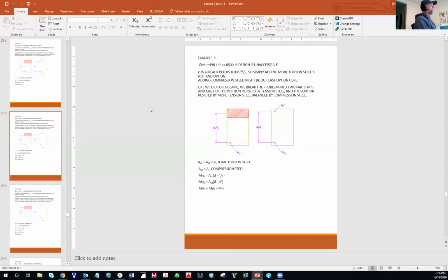Your live load, whether the live load is over the whole span or just the cantilever or just the backspan, you multiply wherever that live load is by 1.6. Now that you have a factored dead load over the whole span and you have a factored live load over the whole span or just the cantilever or just the backspan, for each one of those cases, you now solve for your reactions and draw your moment diagrams.